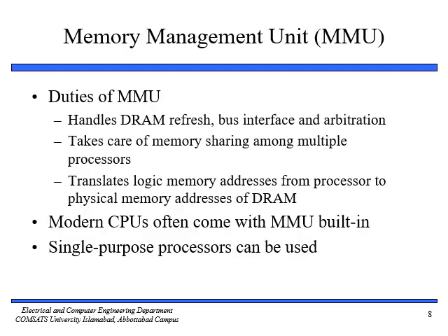In this slide we are going to talk about the memory management unit. Duties of the memory management unit include handling DRAM refresh, bus interface, and arbitration. Arbitration means to settle disputes. It takes care of memory sharing among multiple processes and translates logical memory addresses from the processor to physical memory addresses of DRAM.